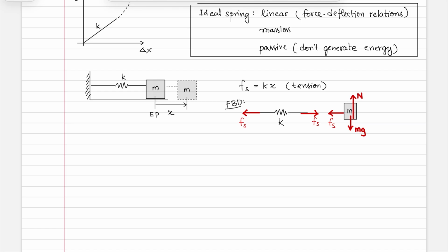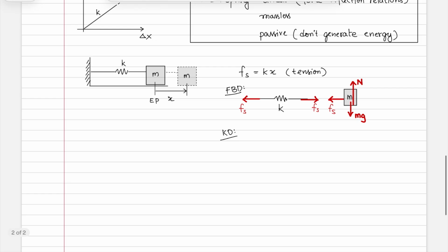So you have the system being defined as the mass and the spring. And now for every component, you have first drawn an exploded view, and then you have looked at all of the forces, and you now have arrived at this. In the kinetic diagram, you want to capture all the inertial forces, which for the spring does not exist because the spring is massless. So you don't have to draw anything for the spring.